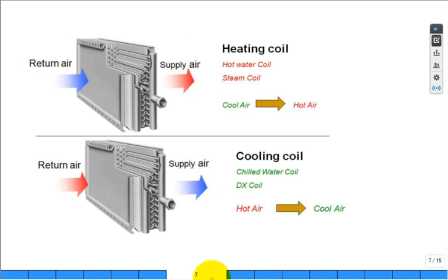Okay, and so they'll bring in hot water, and they'll also circulate it back. So it won't go back as hot because some of the heat is transferred out of that hot water. What's it do? It's heating up air. So the cold air from the room in the middle of winter gets heated and then dumped back into classrooms like this, and it's warmer. Warmer air comes into the vent system. Okay, so that's a cross-flow heat exchanger. That's all it is. We have all the tools to analyze it. We can size it now. We can rate it now.